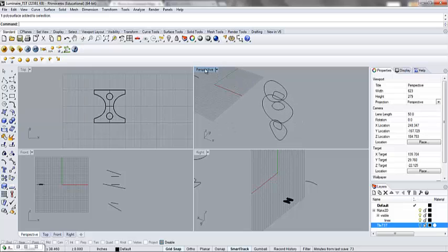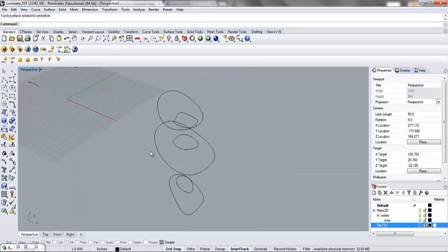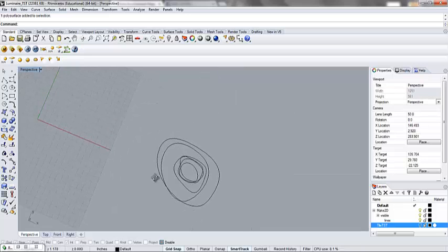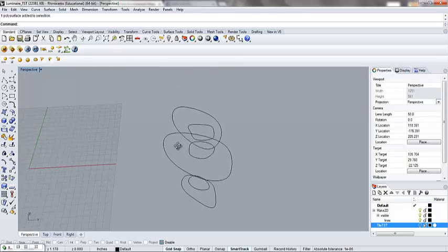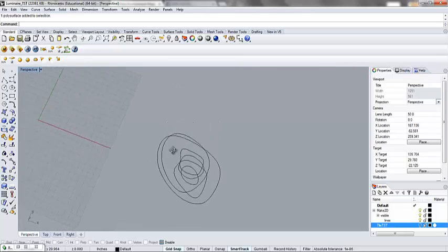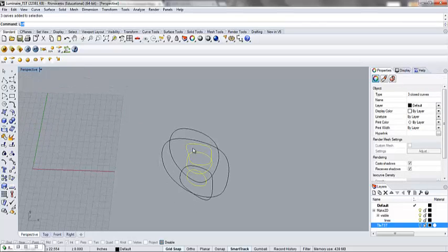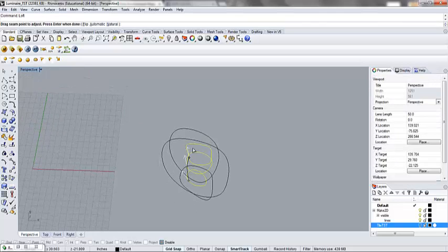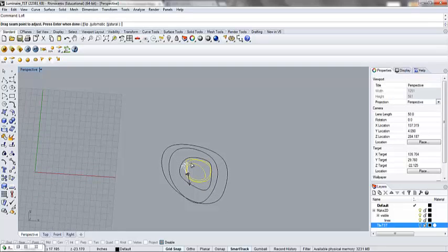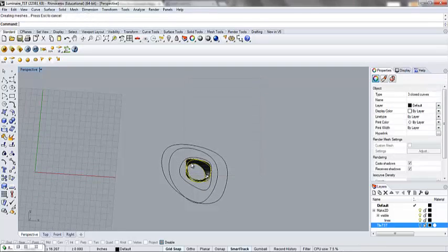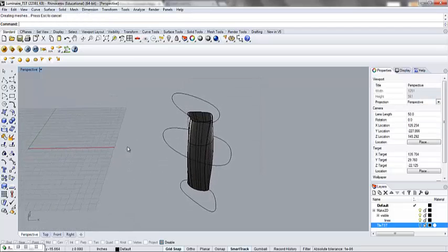And so what we can do is, I've modeled two surfaces here, or two curve frameworks for surfaces. So we're going to do this a little bit differently. Instead of using the offset tool and generating derivative surfaces, we're going to model two surfaces, and those are going to generate the luminaire here. So I'm going to go ahead and loft this, select this interior surface. And you can see the seam is right there. So hit loft. So that's going to be our interior drive surface.